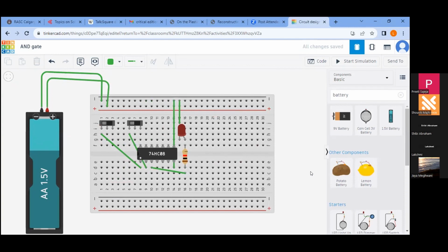Okay. So one mistake I can see is that terminal two of switch 2 has been shorted with another terminal of your gate. If you hover over the terminal 2 of switch 2, the other side, here? Yes, both are connected. See, ma'am, a small line is showing, which means they are connected. It's the principle of the breadboard. They are ideally connected.